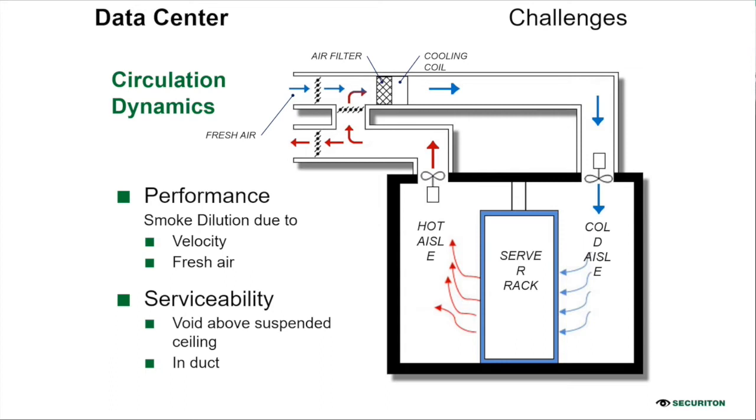The hot air will cool. Cold aisles refer to the rows composed of rack fronts. Cold aisles face the direction of the air conditioner, meaning when you open the door, you will always find a cold aisle. Meanwhile, the hot aisle faces the direction of the air conditioner return ducts, where your exhaust system is. This cold aisle containment system is used to isolate them from the hot aisle.